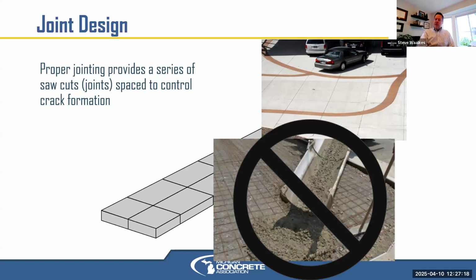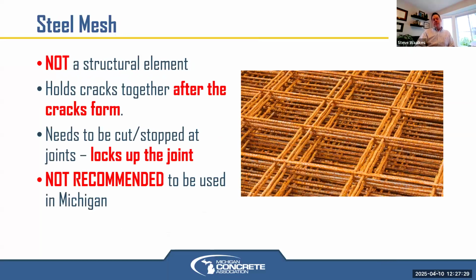We've gotten away from using wire mesh in concrete in our state. Thankfully, I still see it used occasionally, but it generally interferes with the working of those joints. So it's not recommended by us or by most folks. And if you want to debate that, we can take that offline and talk about it later.